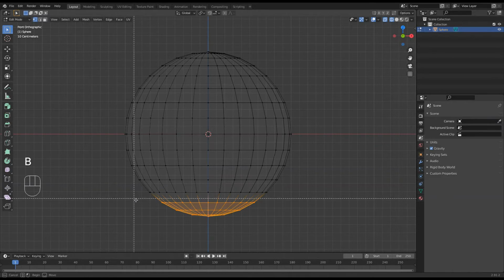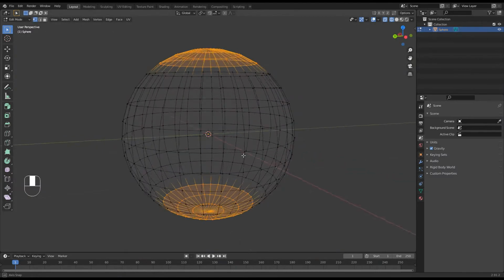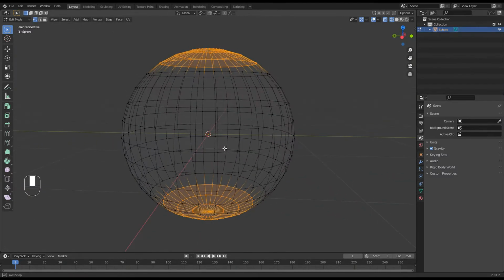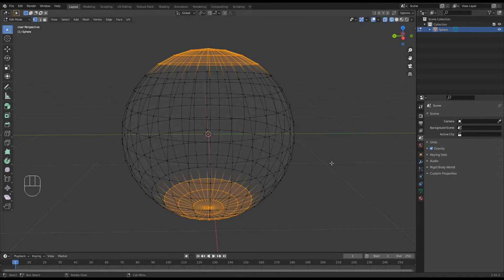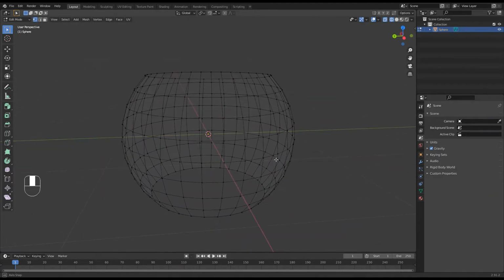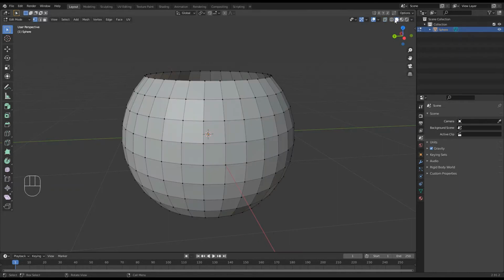And if I go box select and go across it again, or at the top here, across it again, now you can see that the view goes right through because it's transparent. So then I can press X and delete the vertices there. Okay, it's a bit difficult to see what's going on in wire view, so you go back to solid view. So it's these two: solid, wire, solid. Okay.